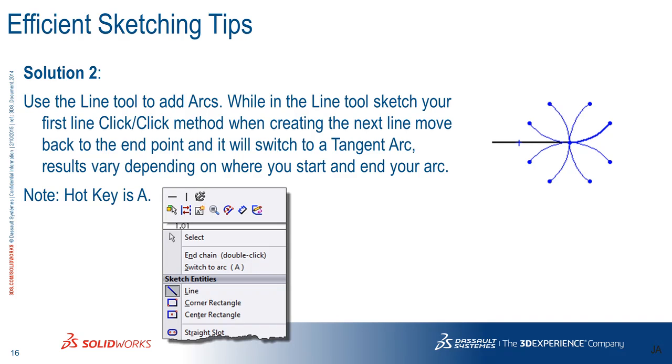And for people who accidentally get into this, the hotkey for this is A, and you can see that in that other screenshot there. When you right-click, you'll see switch to arc or switch to line. A is the hotkey for that.